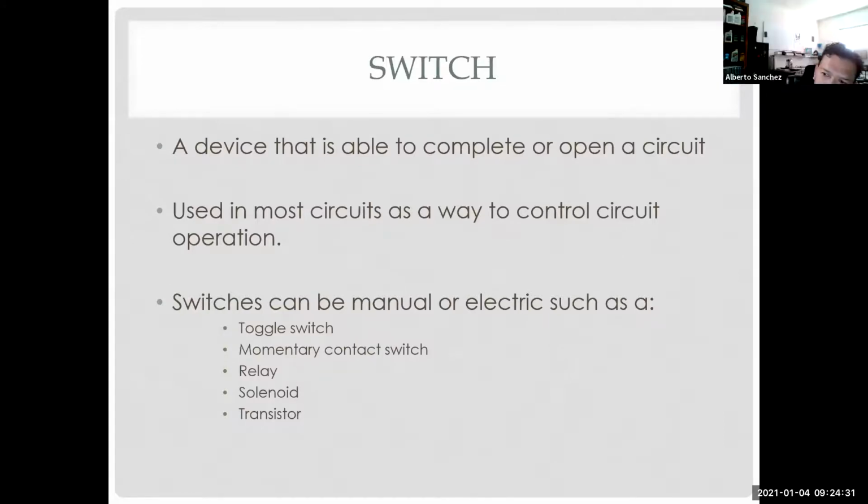It just came to my mind that for a starter, you use a heavy gauge wire, and usually the wiring at home is thinner than the one for a starter. Yeah, and the reason for that is because of Watt's law that I'll get to. Watts is work, and watts is volts times amps. So as I increase voltage, I need less amperage to do the same work.